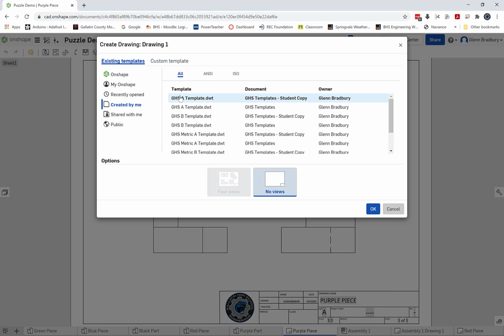As far as the three-dimensional view up here, we really don't care all that much about what its orientation is, so it's not a big issue if it gets sort of weird. But in this case, again, I have a hidden line here, I have a hidden line here, so I'm not gaining anything by changing it. You can go ahead and check all of the views that you want and see if you can figure out a better one. I'm going to go ahead and put this back to the front view that was already there. At this point, you'll see the views have moved a little bit, so you might want to move them back where you want them.